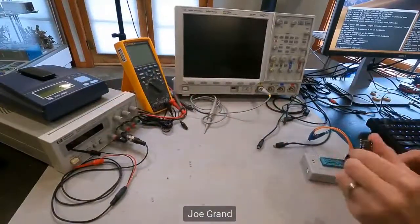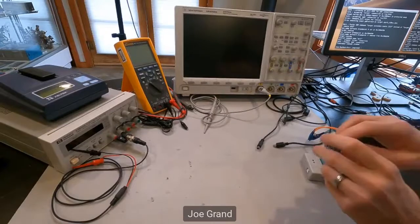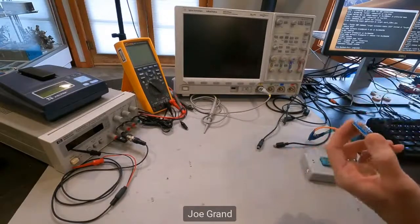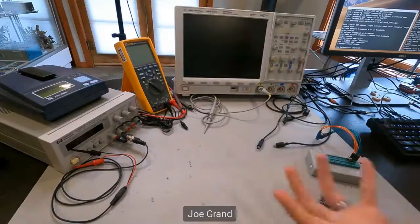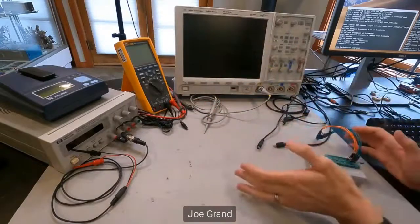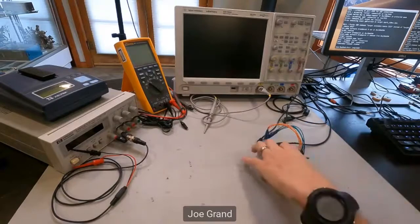But if you know the particular device you're working with, you can find some open source tools as well. One of them we're going to be using later on, and I'll show some examples of other stuff that you can do. If you know the protocol and the memory device, you can use a software tool like flashrom. We'll read some of them. There's actually some open source code for this device as well, because this is a Windows tool, as you'll see. So there's a lot of work in this space, but since I do this so much, I just want a tool that's going to do the job for me and not have to mess around. So getting a device programmer is a highly worthwhile investment, because you make sure the device programmer works with the memory device you're working with, and you're good to go.